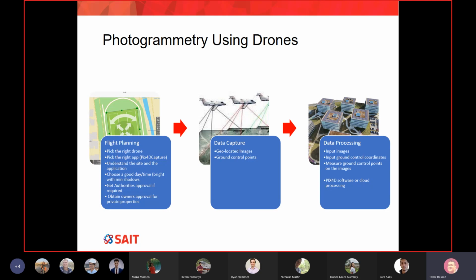How can it go to this specific location? Only because we have a GPS. But the problem is, if there is something dangerous for the GPS signal, like power lines or trees, it will interrupt my GPS signal. Then I have to be away from those power lines and trees when the drone lands or takes off.